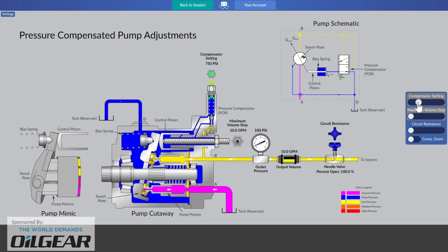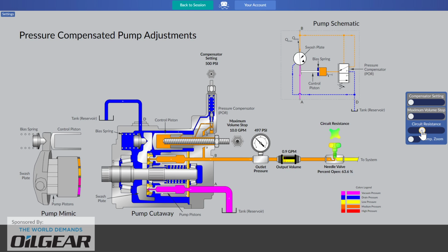If you make a few turns with a wrench and a gauge doesn't follow you, probably something is wrong with your procedure or something went wrong with the control. Put it back. So keep track of how many wrench turns that was for safety's sake. Let's put it back and start back to where we were. And now very carefully, we're going to close in and blind out the flow of the pump. I'm just closing in the needle valve over on the right-hand side of the screen.